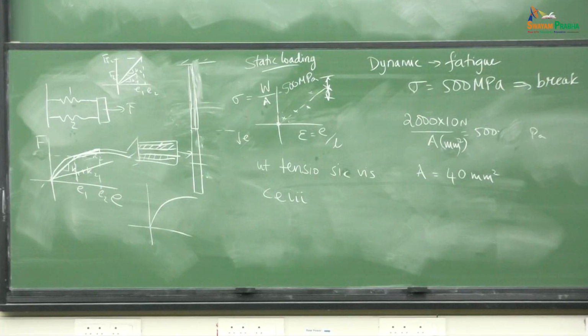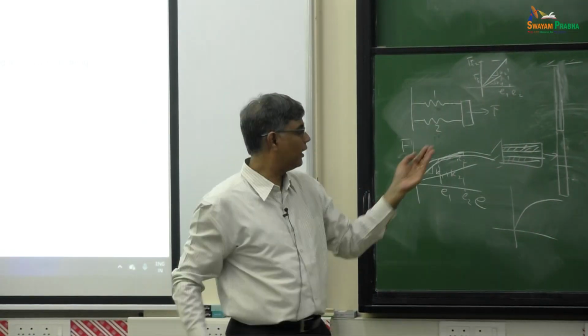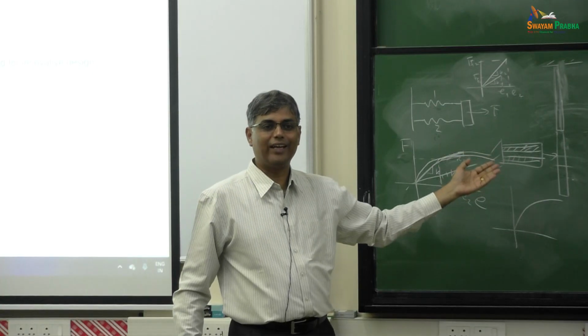The difference in K is because of the deformation inside the object itself. So can it be done like scanning the body? Very good question. So identifying where the deformations are and accordingly adjusting our standard K value to those values. So his question is, is there some other way? So here I am doing a bulk deformation. I am just taking this little bar and pulling it overall and finding out how it overall extends, and from that I am trying to find some local model of the K1, K2 and all that.